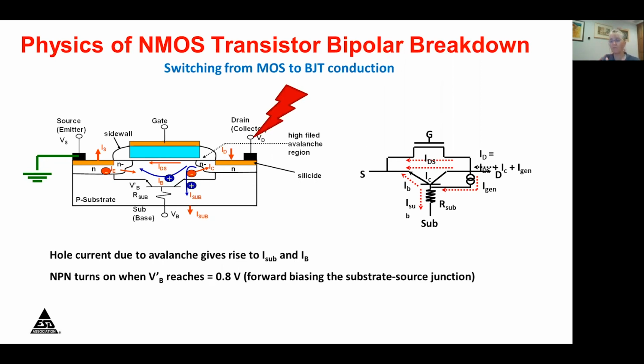So when you look at a MOSFET, for example, the normal care-abouts of a MOSFET relate to controlling the gate so that the switch is on or off, the drain current is high or low. When an ESD engineer looks at a MOSFET, they see the parasitics. And in any MOSFET, there's also a parasitic bipolar. And if we can leverage the parasitic bipolar, then in the same area, we can use that to conduct much higher ESD current than if we were just using the MOS.